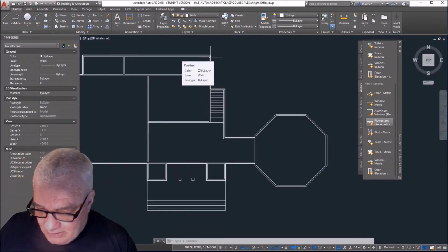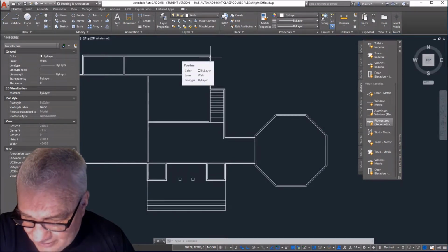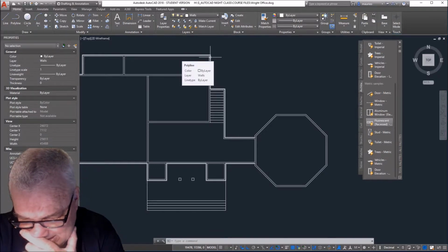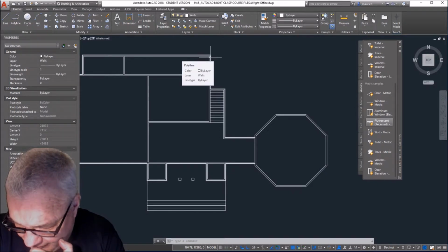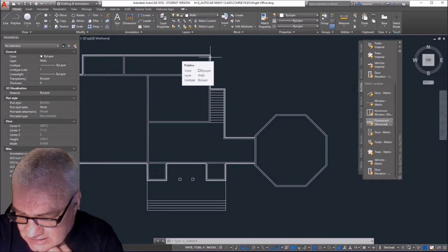Okay, now create the openings for the doors. Should be 900, and the single doors 800, and select the architectural tab and add the doors and windows. Use grips to modify the locations, lengths and widths of the doors, and swing of the doors. Use mirror to create the double doors, and quickly add windows in the library. Place 2 along one wall, and then use polar array. Erase the windows where the door is needed.